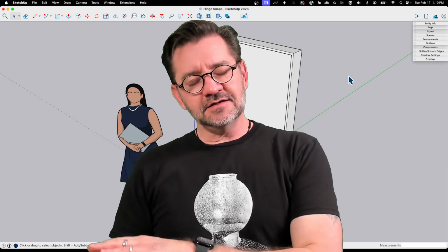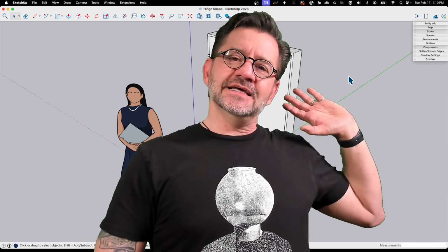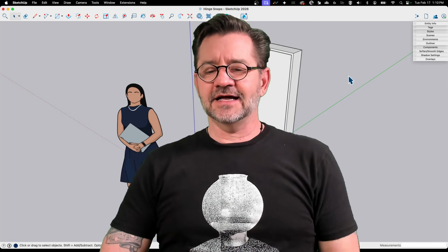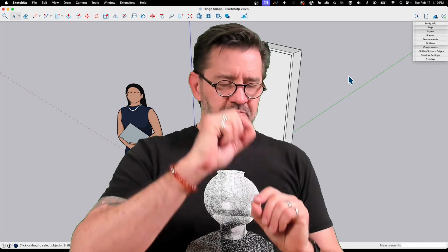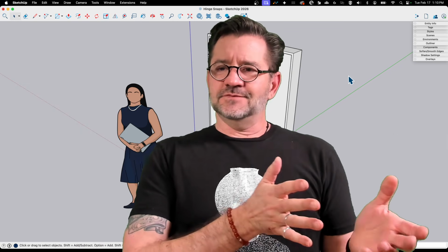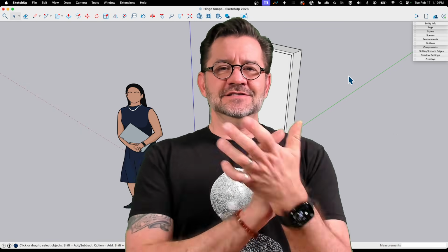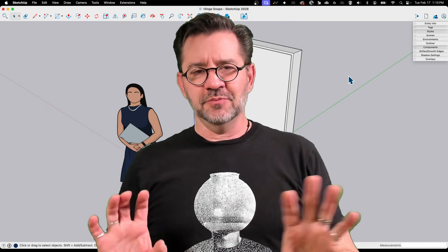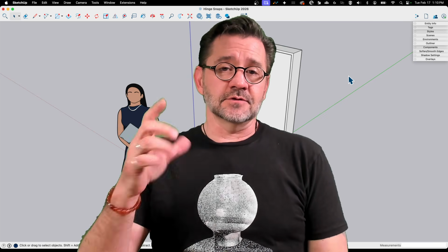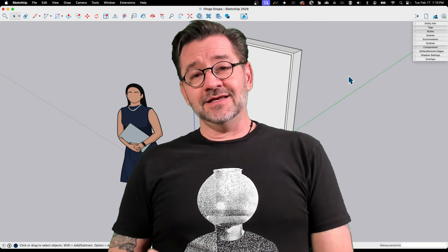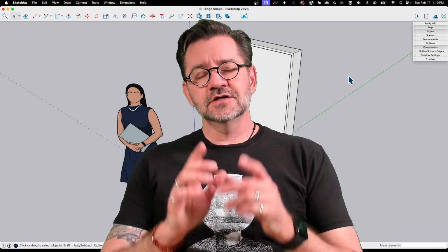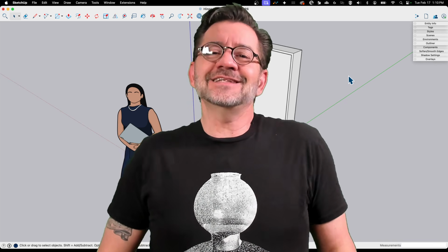So again, shout out to all of my dynamic components fans out there. You guys are awesome. And yes, you could have done all that and then set the axes at the middle of the pin and then say on click, rotate 0 plus 15 degrees up to a certain amount and then go back close. You could do all that. Or you could put a dot in there and just rotate it open and closed. My opinion, that's probably quicker and easier. I don't have to interact with it. I can just use my model tools, but you do you. This is an option. That's all I'm saying.